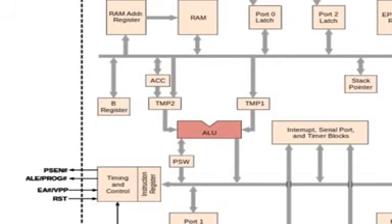The format of this operational code is, we write the instruction first, which represents the operation. After that I write the memory locations where that operation is being implemented, in the form of source and destination. After writing the instruction, first we write the destination, then the source. Now if I wanted to write ADD A, B, where A is one register and B is another register, ADD is the instruction for addition in 8051. So I'll write ADD A, B.